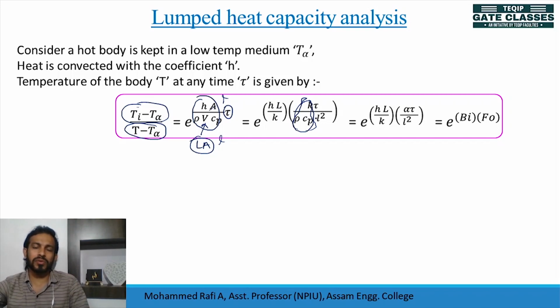Regarding thermal diffusivity, we are going to discuss it in the next lecture, which is steady conduction with heat generation. There we will discuss more about the physical relevance of thermal diffusivity, why alpha is relevant, and how we can differentiate materials with respect to alpha, because alpha is a thermophysical property, just like thermal conductivity, whereas the convective heat transfer coefficient h is not a thermophysical property.